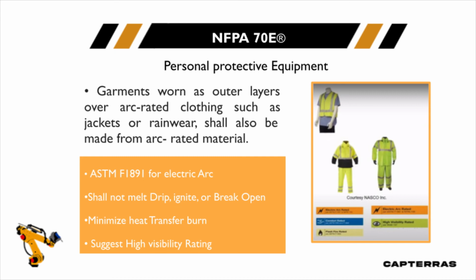And I see it all the time. People wearing hoodies, polyester cotton hoodies over the top of their arc-rated clothing. They're compromising their protection. And in many cases, they may not have hardly any protection, because that type of hoodie will just catch on fire, burn, and melt.